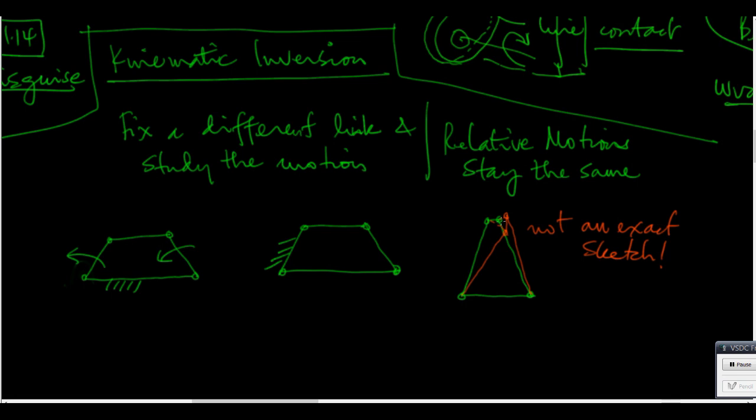Now, then there will be a situation where this one has gone like that, this one has gone like that, and that intervening little link has turned through 180 degrees. In this way, the little link can turn through 180 degrees, and these links are just gently rocking, while that one is going round and round.